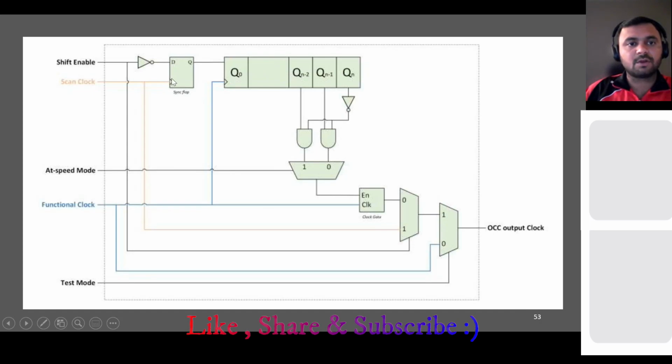So basically you have a flop here where you put the shift enable, and you have the scan clock. This scan clock is nothing but your slow clock. You give this to this, and it also goes to this mux. And then you have a functional clock as well here, which will come from the PLL. So you need some flops. As I told, you need 2 different pulses during the capture, so you need some mechanism to generate those pulses.